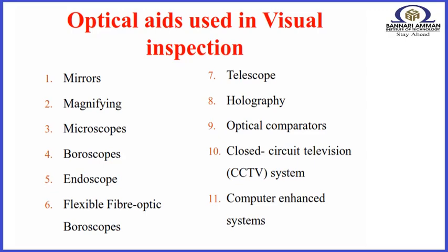Mechanical aids include measuring rules and tapes, calipers and micrometers, squares and angle measuring devices, thread, pitch, and thickness gauges, level gauges, and plumb lines. Welding fabrication uses fillet gauges to determine the width of the weld fillet, undercut gauges, angle gauges, skew fillet weld gauges, pit gauges, contour gauges, and a host of other specialty items to ensure product quality.